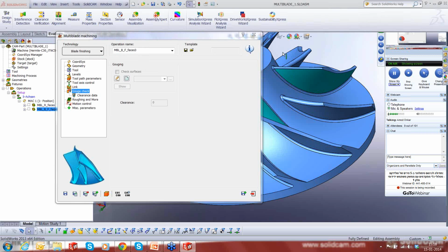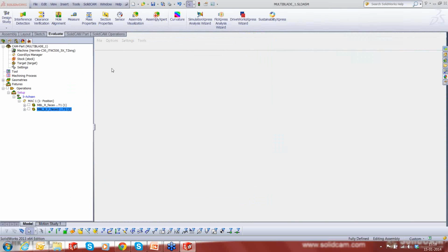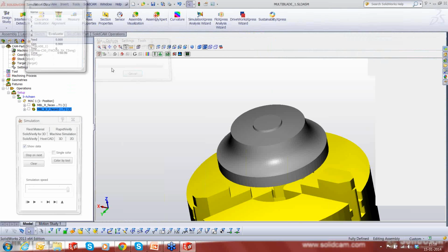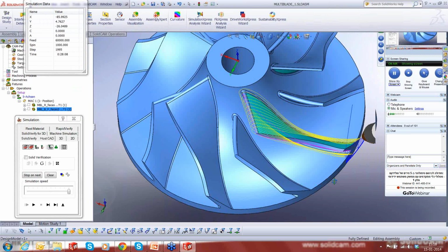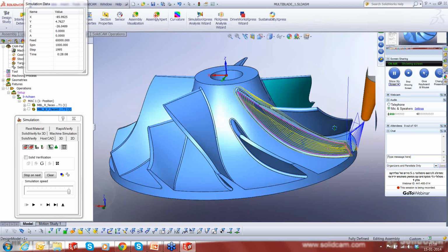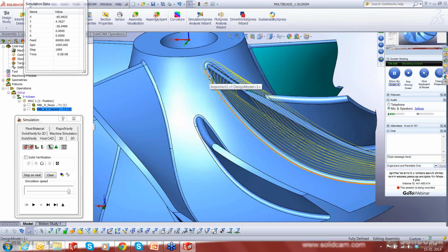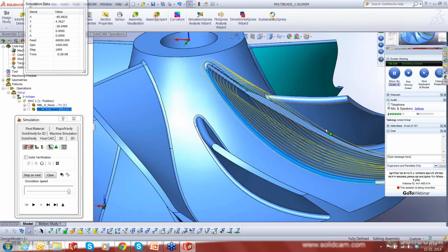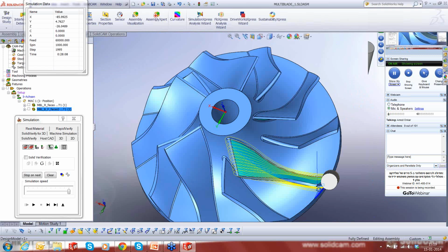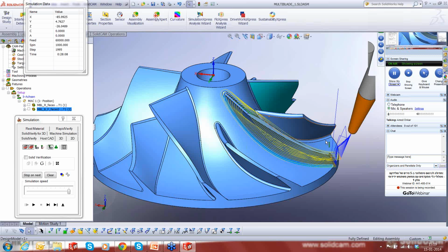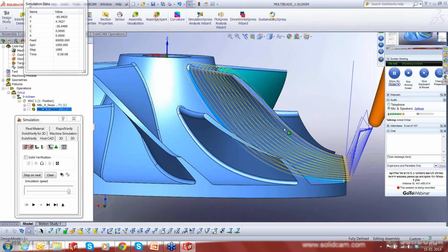Okay, it's finished the calculation of the finishing programs, and if I run not this but the host CAD, you can see very nice toolpath, straightforward toolpath. We didn't do anything. We even included the fillets below as our cutting surface, and the software did it perfectly. There's absolutely no flaw in machining. It's a clear, smooth toolpath.